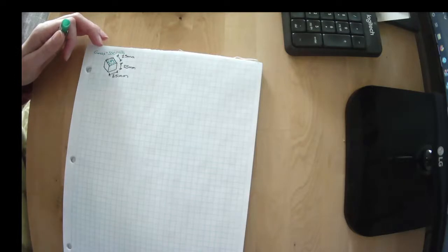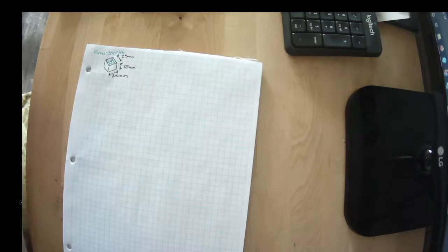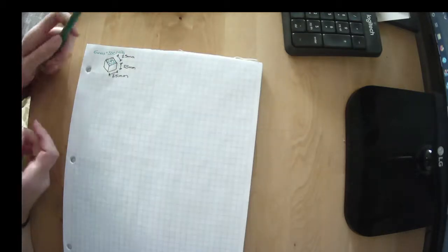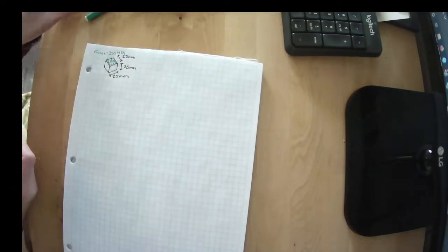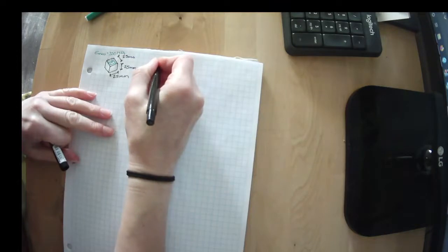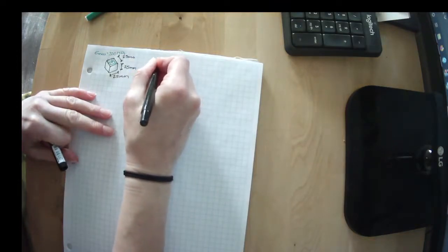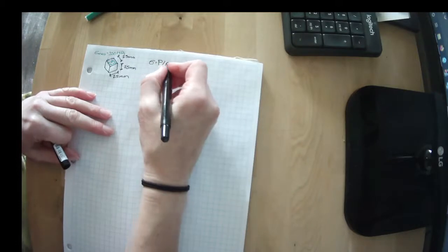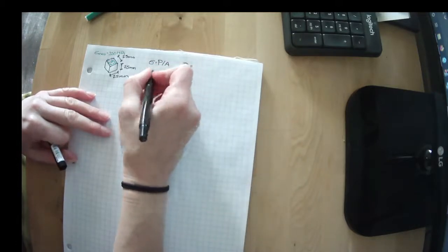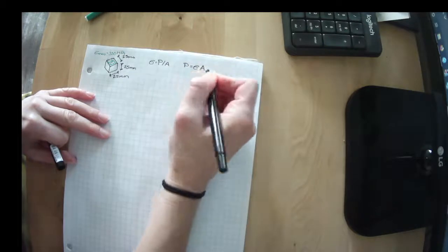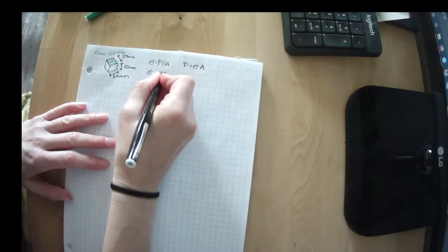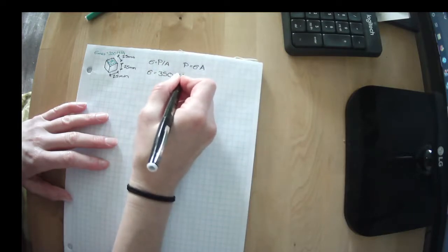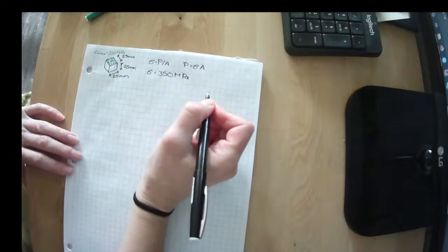We want to know what force that equates to. What's the maximum force that this 25 by 25 by 25 piece of steel can support? Well, we know that stress equals force divided by area. We want to know a force now. So force equals stress times area. We already know that the maximum stress that it can take is 350 MPa.